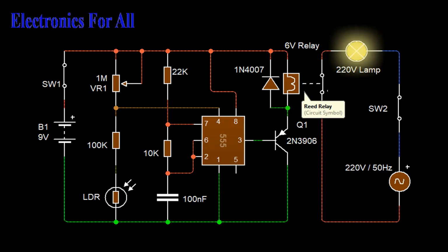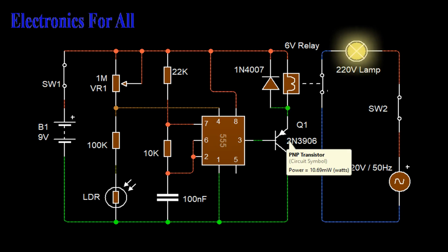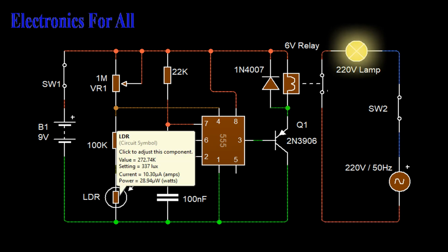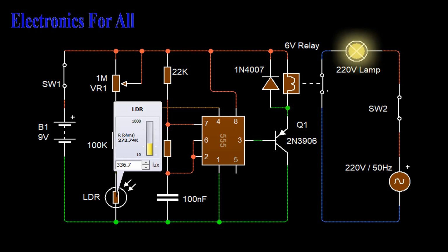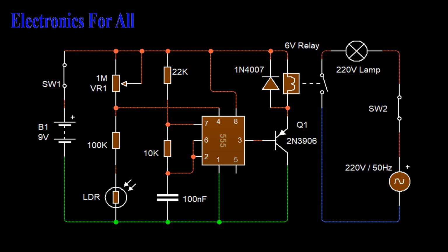The transistor here drives the relay, because driving the relay directly from the IC is not a good idea. The purpose of a diode connected in parallel to a relay coil is to avoid damaging nearby components sensitive to high voltage. This voltage is generated in the coil when the current flow is interrupted. The diode allows the current flowing through the coil to continue circulating when the relay is deactivated. The relay here can be replaced with LEDs to create an output response of lighting, or replaced with a speaker to work as a darkness alarm.